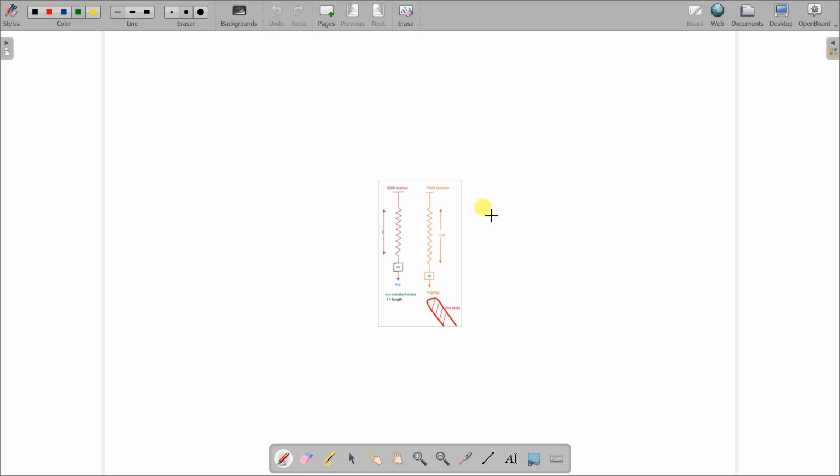The modern gravity meters are used to find the relative gravity values in a particular place. They have a spring balance with a known mass. This mass is known already and it is placed at different places on the earth. The place where you have some subsurface body, the spring will be stretched down. So this will indicate there is a change in the gravitational attraction.